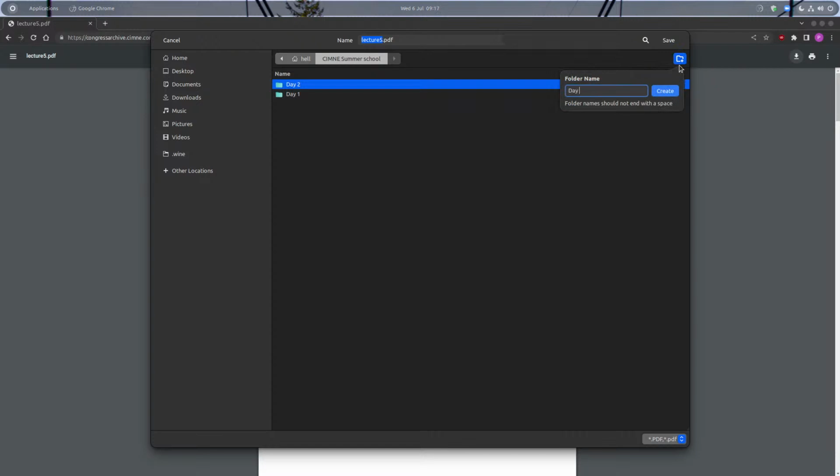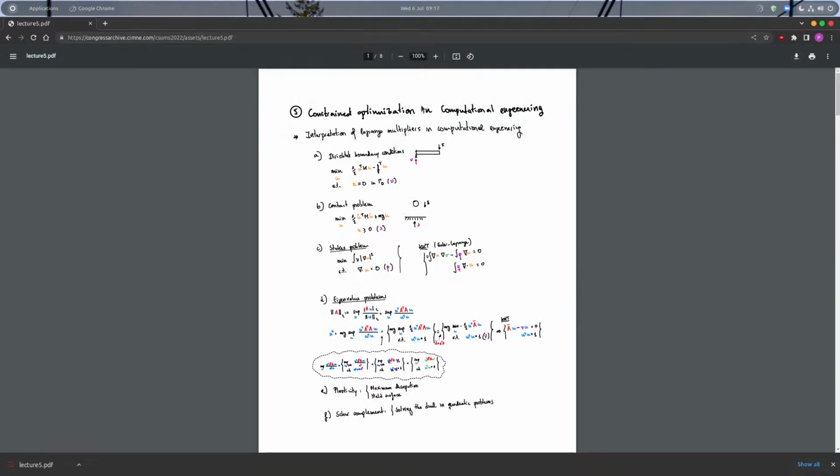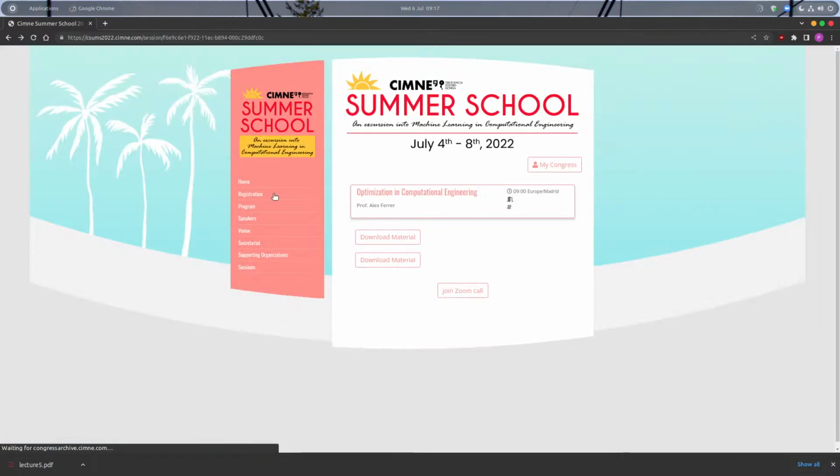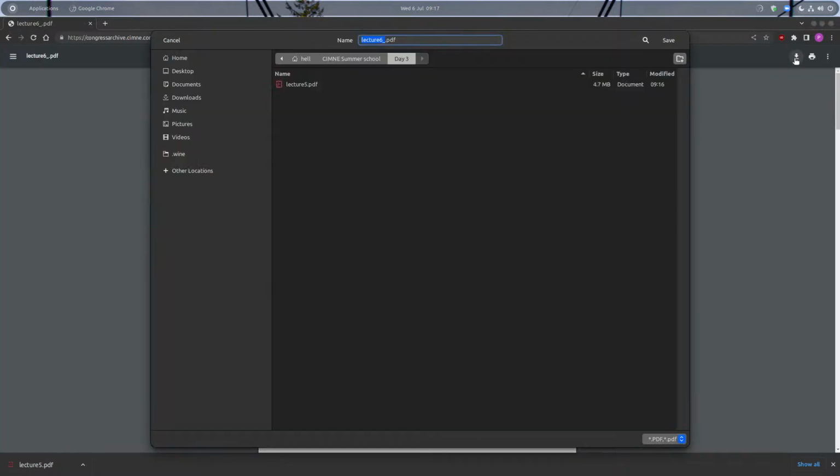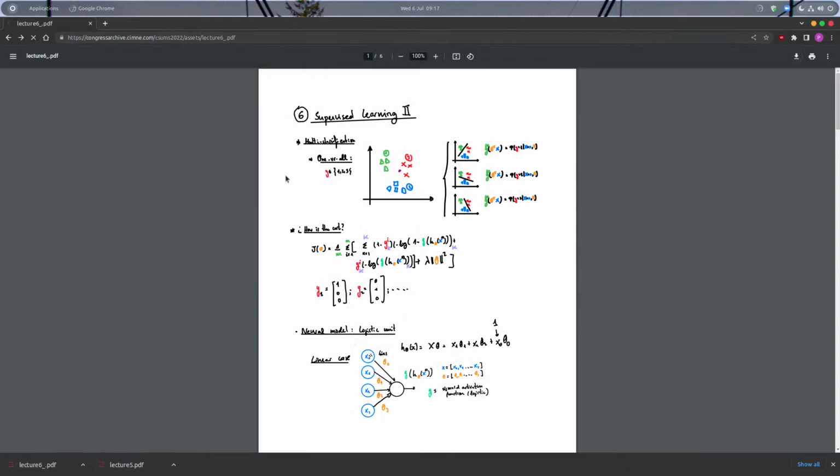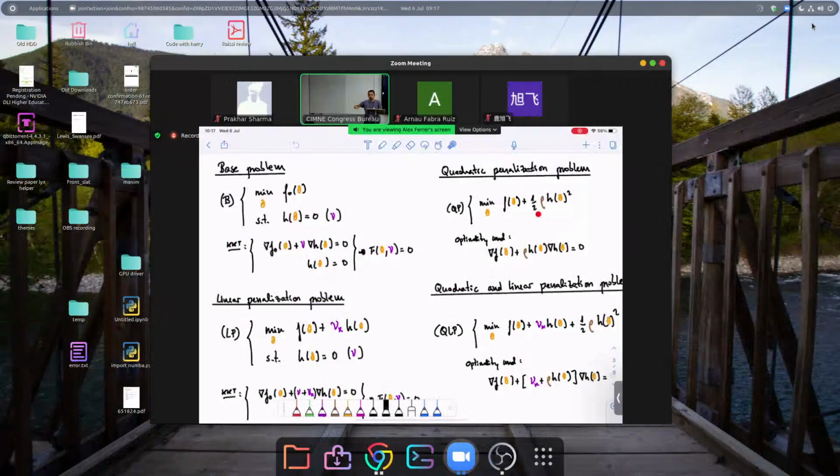And what did you add? You add a parameter that is called penalty parameter, rho. Probably you have worked in penalty methods. So people who are working in penalty methods, they do this. And this is the penalty parameter. You want to stabilize the divergence of U in Stokes. You penalize it with this, and you don't have any more the pressure.